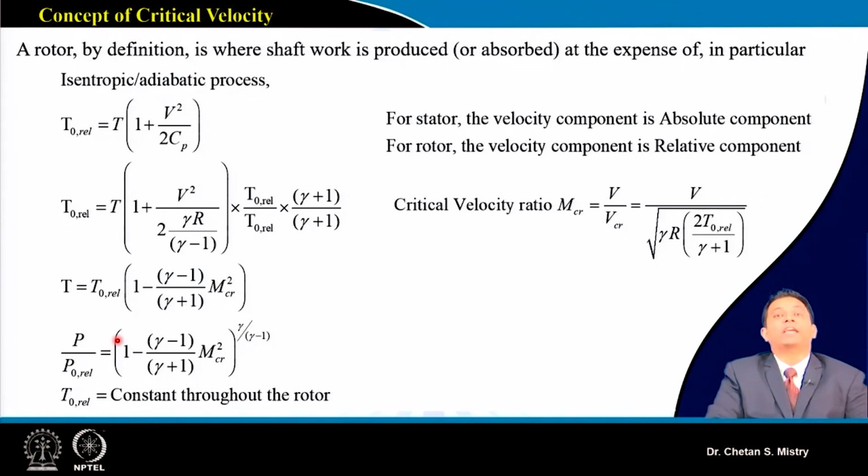One we can call the sizing problem. When we say it's a sizing problem, that means you are given some input parameters: your entry condition, the rotational speed, and the pressure rise that you are expecting. For that we will do our design for the rotor and stator with the whole process that we have discussed till now. So based on what we are expecting, we are doing our design. That is defined as a sizing problem.